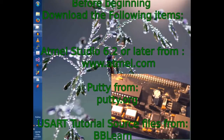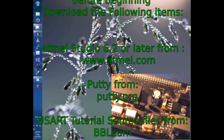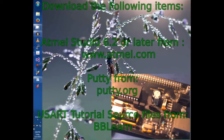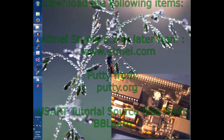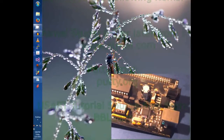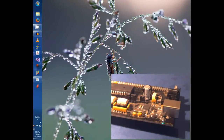It can, however, also be used for SPI data transfers with the microcontroller in a slave mode. Channel B can be configured as a virtual COM port that is physically connected to the Atmel Serial Communications Interface USART 0. Before using this, you must configure the development board for serial communications over the virtual COM port.